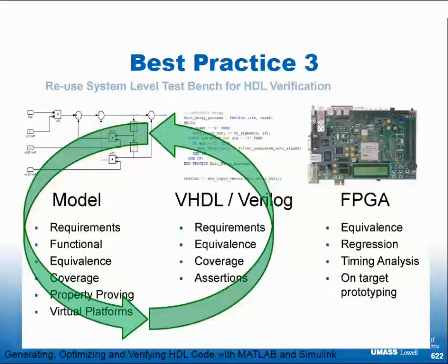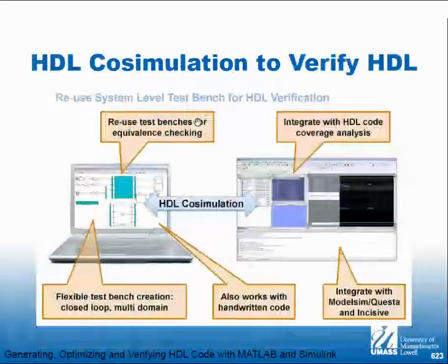It's much easier to do it on the FPGA, but if things don't work on the FPGA, now you're dealing with the logic analyzer and things like that. So it's good to be able to do transactions in both directions in simulation, and then load your drivers and get the peripherals running and all that stuff on the FPGA. All part of verification.